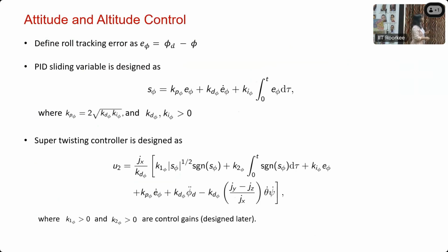And once S1 goes to 0, which means S5 goes to 0, and S5 is this variable, this term equals 0. And then after that, you can use a very simple Laplace transform method, and you can see that this error will go to 0 asymptotically if you choose these gains Kp, Kd, Ki as I had mentioned previously, with the relationship between these gains.